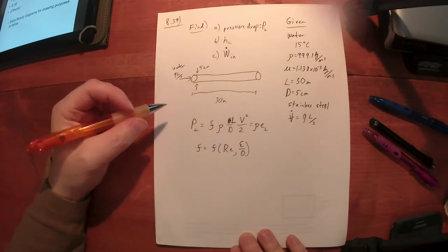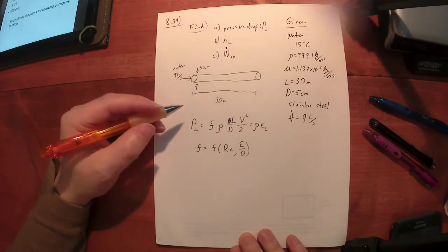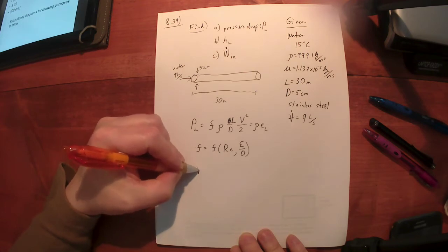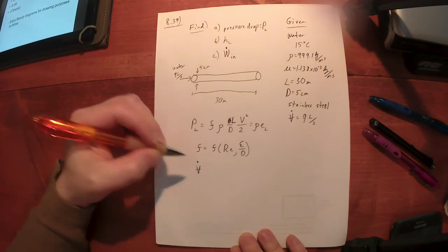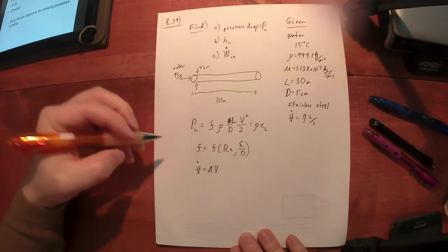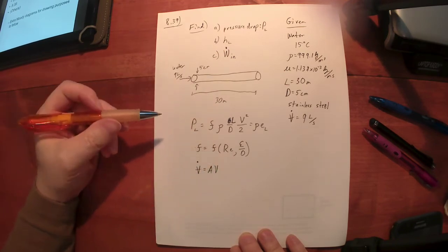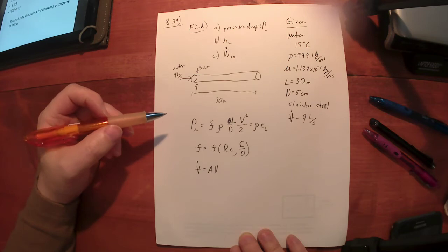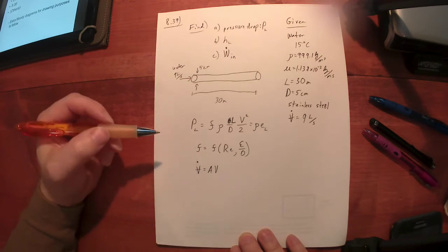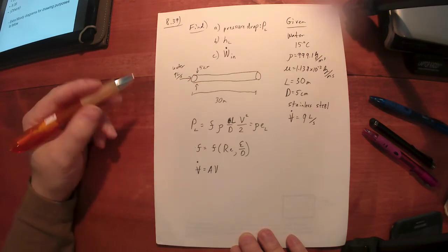And what are some ways to find that? Well, based on what I have, we could find that speed using the volumetric flow rate. By the way, if you're a guest, not in my class, you may use Q. There are a lot of texts that use Q for flow rate. In our text, we use volume V with a dot above it. That's V dot, the volumetric flow rate.